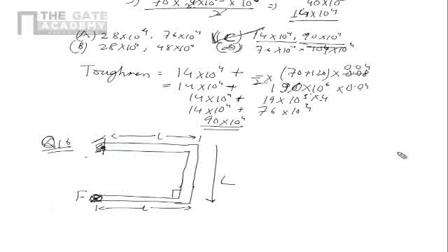How do I find a load? So I transfer the force F here directly. So the F goes like this directly. So the reaction here will be F, and then there is a torque, because this F multiplied by this length will be acting as a torque there, FL. So those are the two things which are acting there, F force and torque of FL. Those are the two things.